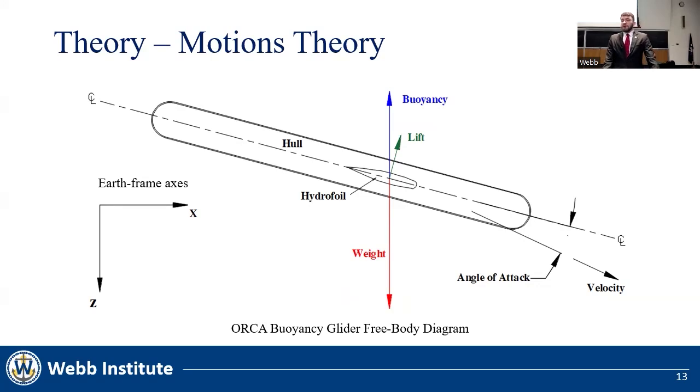As can be seen from the free body diagram, there's only one force that contributes to the acceleration of the glider in the positive x direction, which is the lift force. However, using a careful combination of these forces can allow the glider to propel itself, and this motion can be controlled through the shift of the internal weights of the glider.